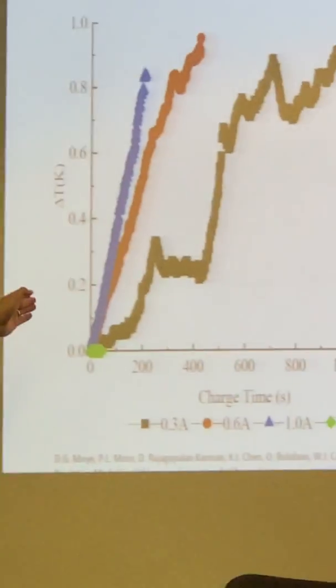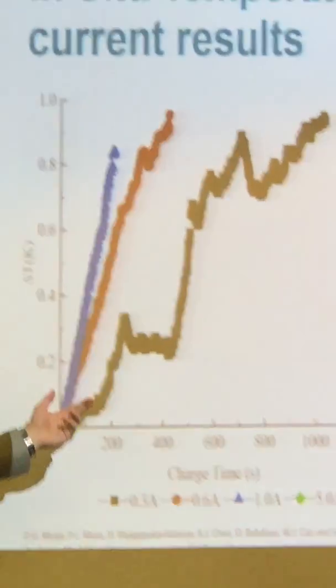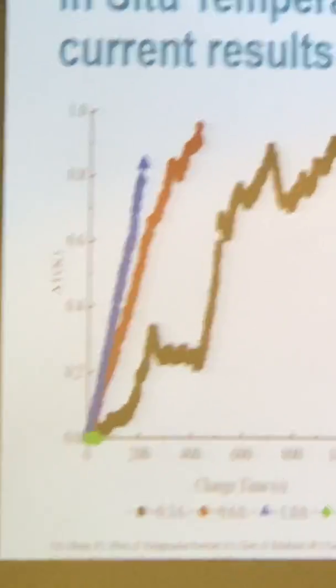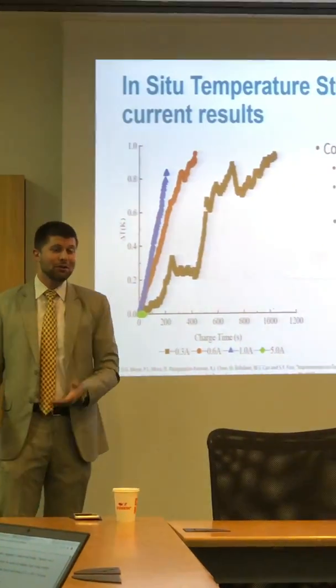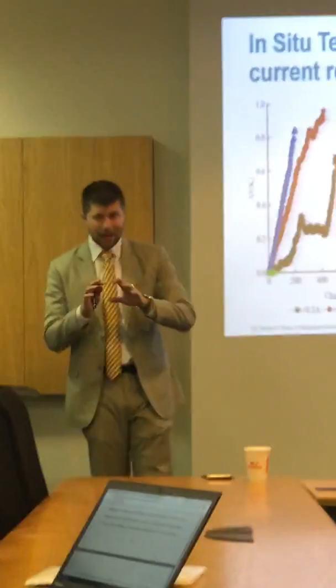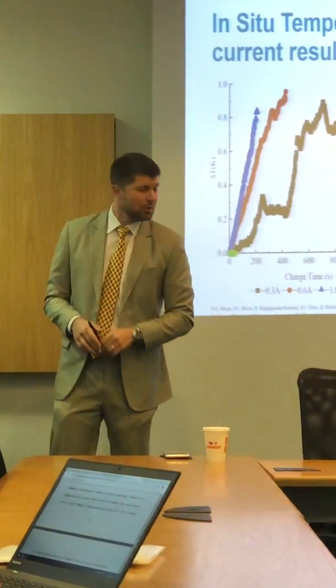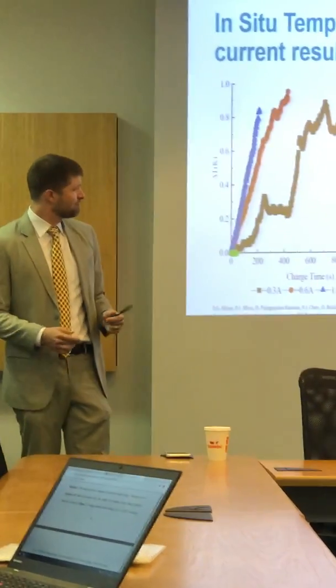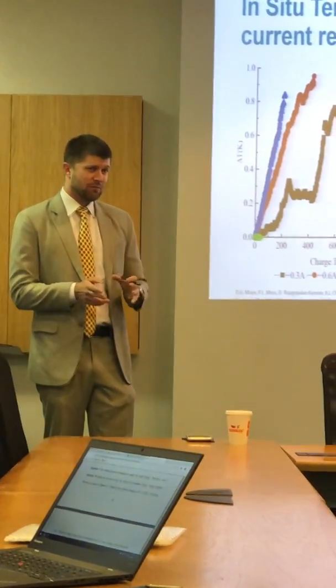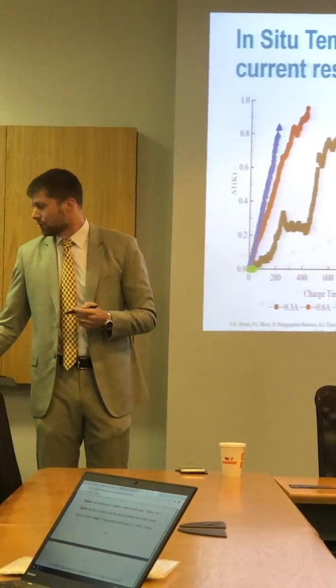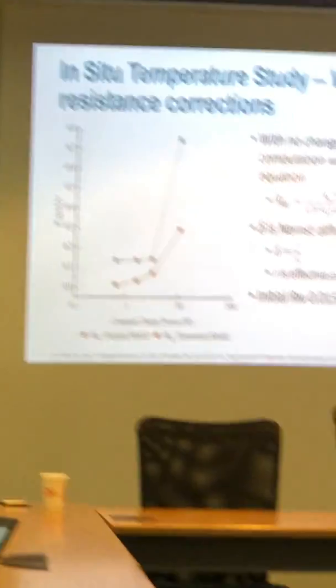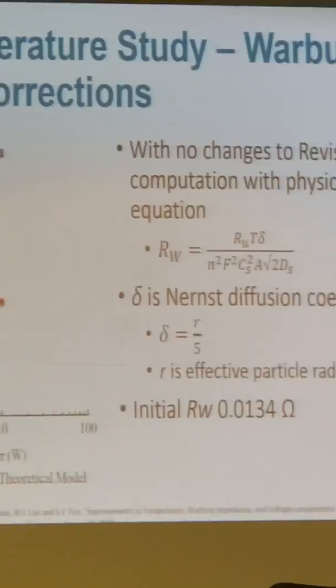And what I found is that if you have a constant current charge, then delta T is actually linear. Moreover, the slope of delta T is linear as a function of your current density. This breaks down at higher power though when delta T is just 0, but the delta T is, at least at low power, fairly easy to predict in these devices. And again, it's not very large. So that was important. For the model to be accurate, delta T's changes need to be minimal.